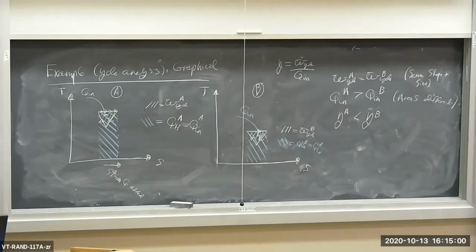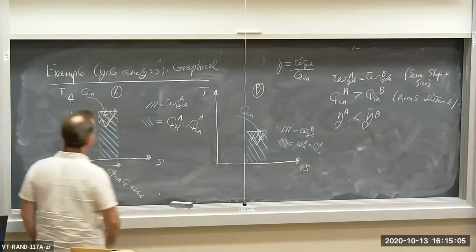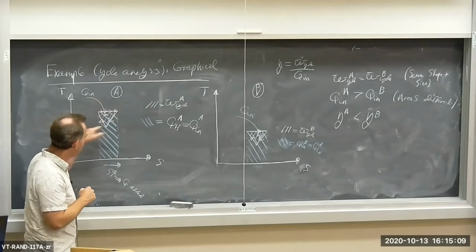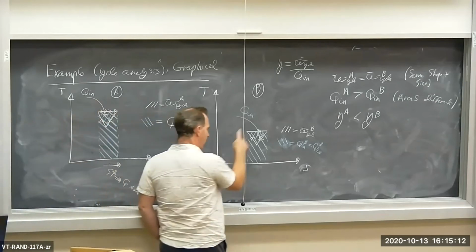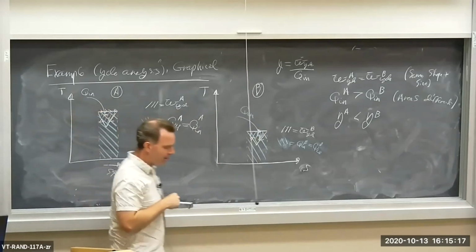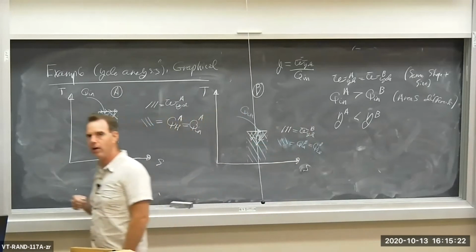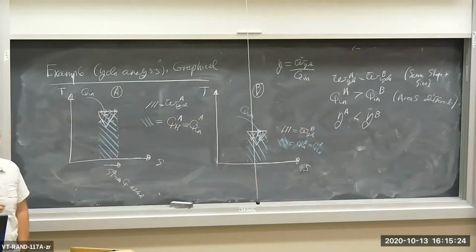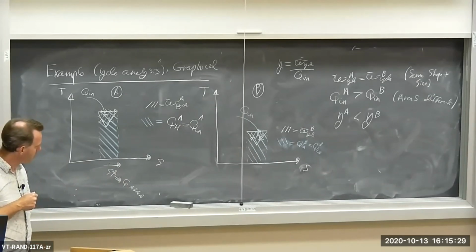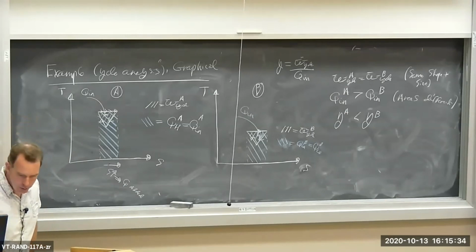So unlike the PV diagram, which only allows us to calculate boundary work, we can get all sorts of information off the TS diagram. The work over the cycle, which is the area bound by the TS curve over the cycle. But I can also get the heat input. And the heat input corresponds to those sections of the cycle, those processes, where delta S is positive, where entropy is increasing. Okay? This is quite nice. Okay, let's do a numerical example here.